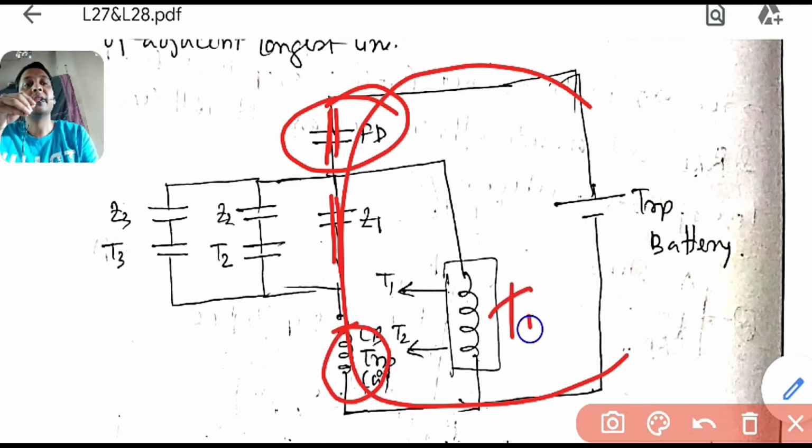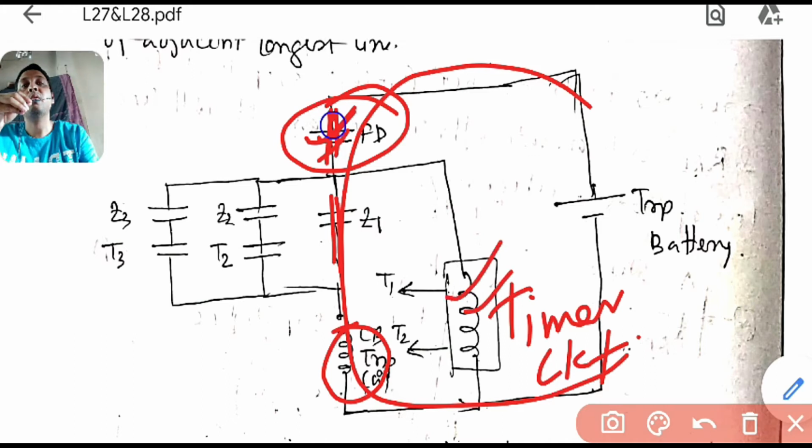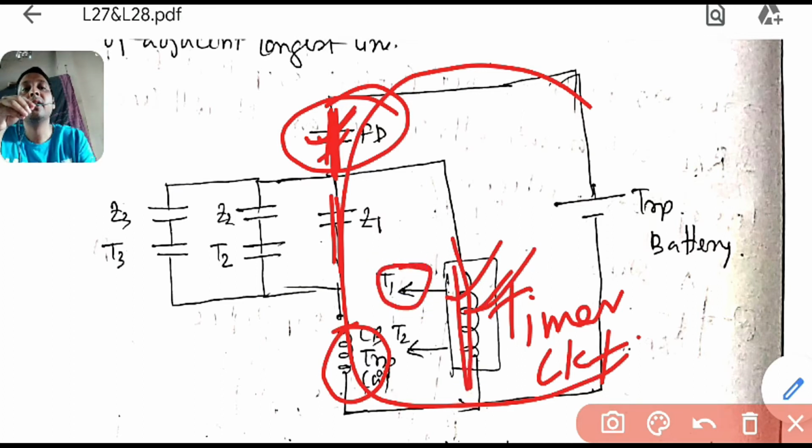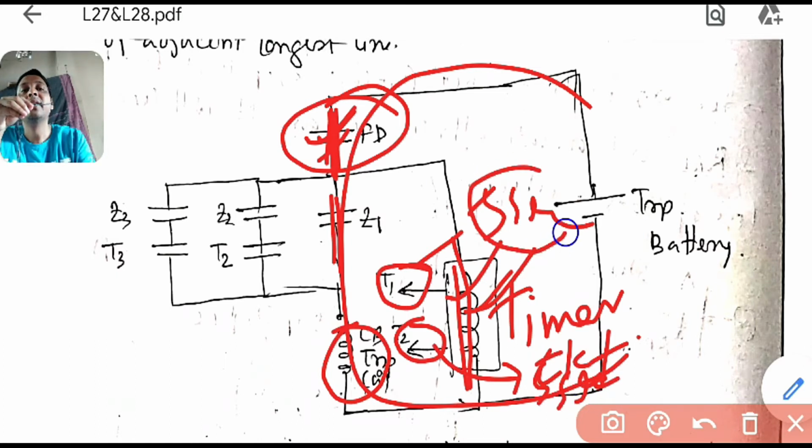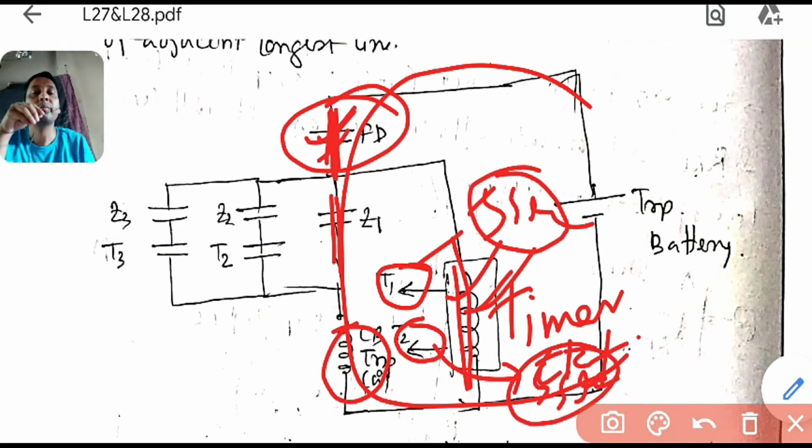And this is actually the timer circuit. Again, it is not written, you can write it down. This is the timer circuit. So once FD is shorted, this timer circuit is activated. Once FD, your fault detector, senses something, it immediately sends a signal to the timer circuit, which is already on, and it will send two signals. One after T1 seconds, suppose 5 seconds, and T2 is another 5 seconds, hypothetically. So it will send a signal after 5 seconds, and again send a signal after another 5 seconds, that is after 10 seconds.